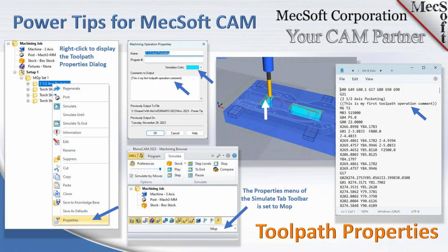We're going to talk about Toolpath Properties. Not many people or new users know about the properties that you can adjust for any given toolpath. If you look on the left here, just right-click on any operation in your machining job. You'll get a menu, and you'll have a number of things you can do. It has a properties option. If you pick that, you'll see this dialog right here on the top in the middle. That is your machining operation properties. You can do a number of things in here that you may not be aware of.